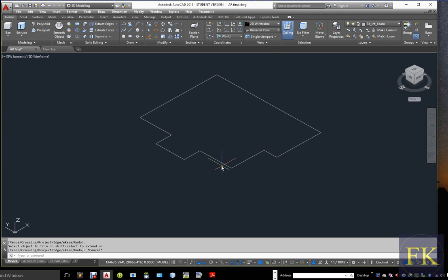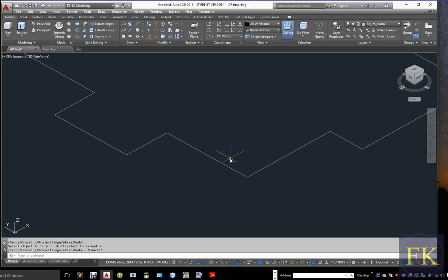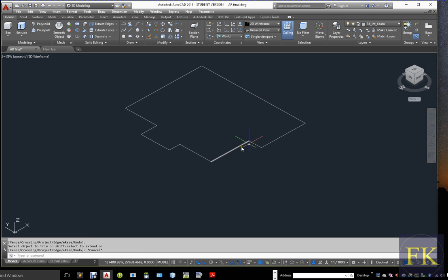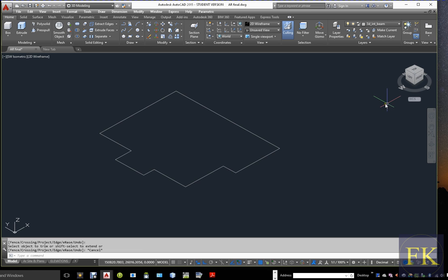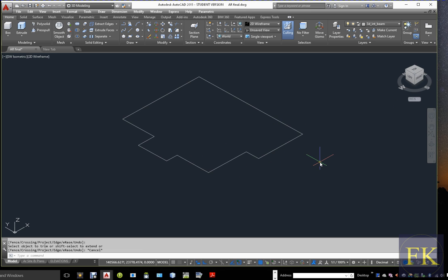All right, and I know this needs to be offset 50 centimeter. Okay, then offset 500 millimeter or 50 centimeter this direction, and extend and erase this. Okay, and trim this. Okay, I know there is a difference between the first floor and the ground floor, that's why I'm making these modifications. Okay, now I'm gonna make my grade beam.